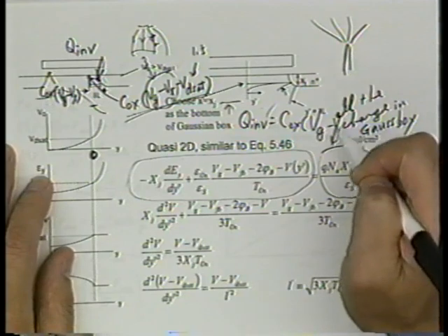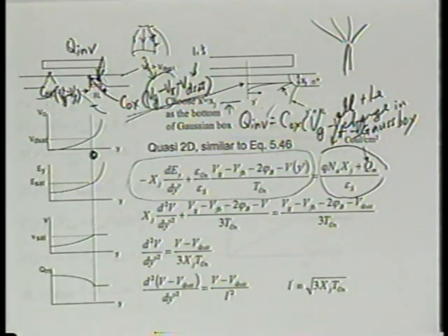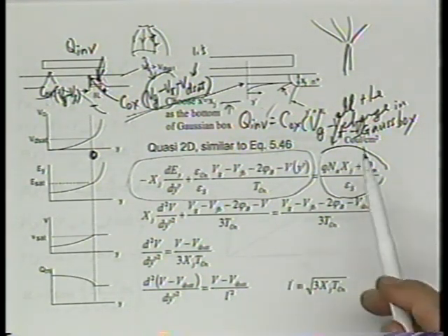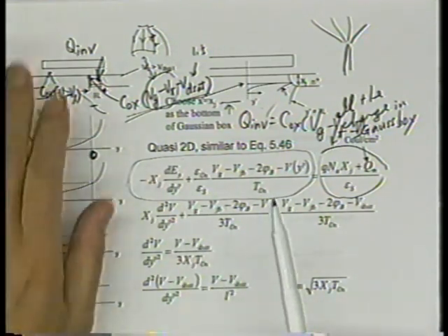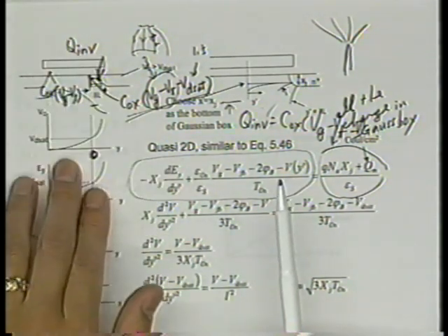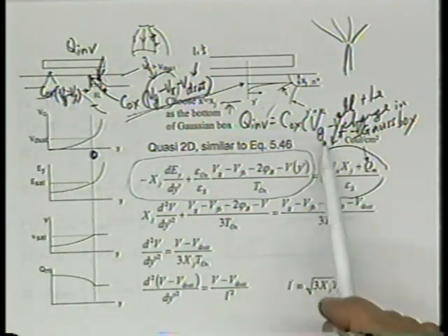By the way, this usual equation we've been using, although we didn't spend a lot of time justifying it, is justified because we ignore this first term. We reduce it to a one-dimensional problem, only looking at the vertical electric field, since the electric field must end on charge. We end up with that.